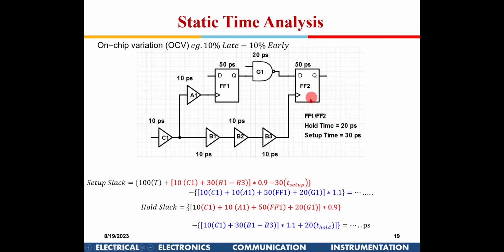Generally flip flops, they don't say, okay, they give this time, but for the gates they generally say, okay, you could apply. So I have reduced the delay in this path for the setup violation here by 0.9. Whereas in the data path, I am going to increase it by another 10%. So all the gates in this path, all the propagation delays here, have been increased by 1.1.